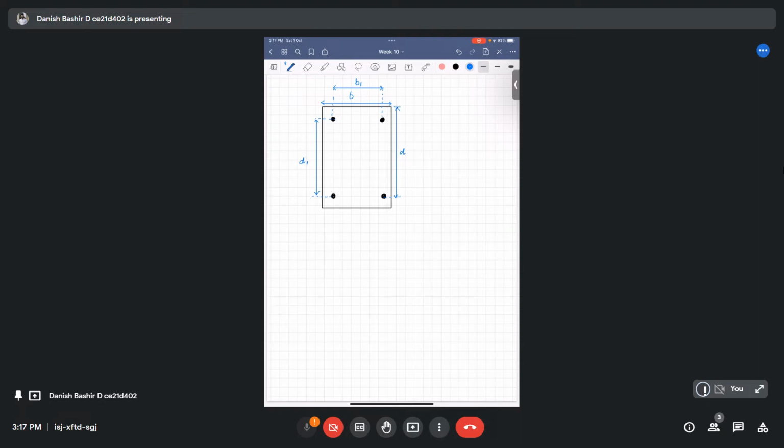Then you will provide a shear reinforcement like this. These definitions are only applicable when there are torsional effects also. We provide shear reinforcement like this. Okay, we define another distance x1 y1. x1 y1 is the outermost face of the stirrup, the outermost side of the stirrup. On both sides we define it as x1.